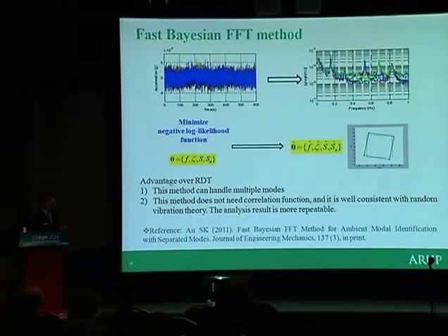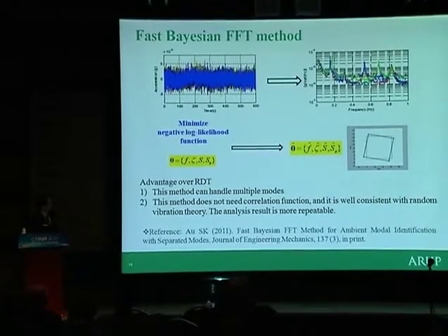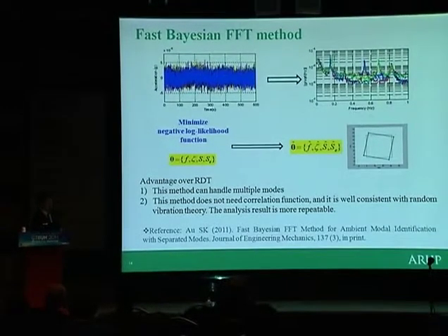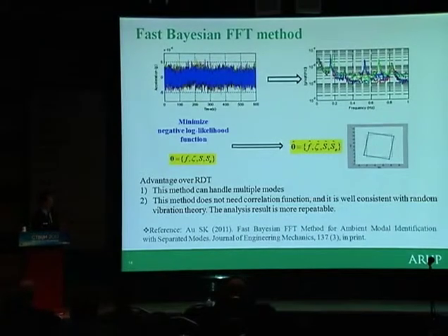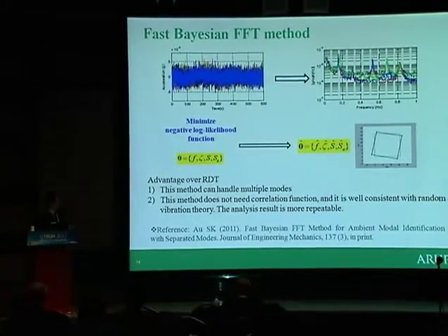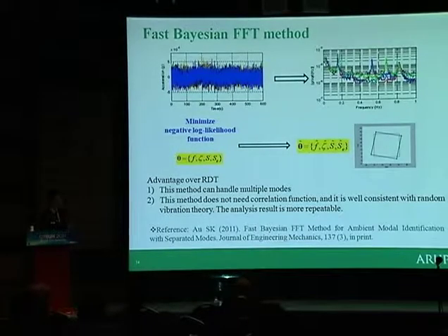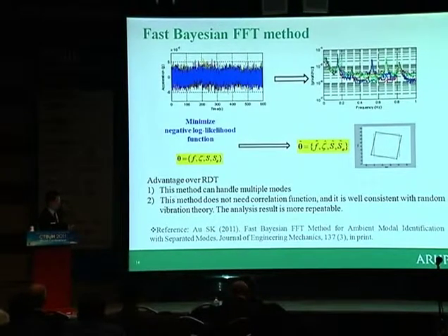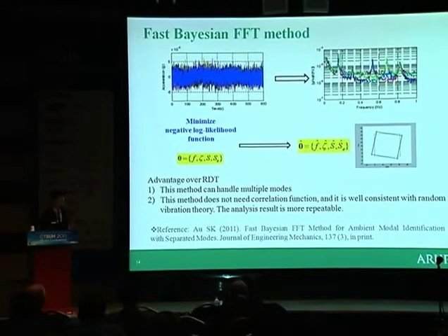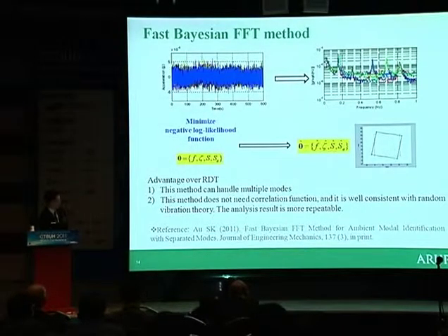What it does is it looks at the wind data and looks for the most probable value, and at the same time assesses the posterior PDF, which in that way, not only can you get the most probable value of the damping ratio, but also you can have the COV, the coefficient of variation of that damping ratio. And that is very interesting and important. If you want more detail about this method, you can refer to the Journal of Engineering Mechanics.